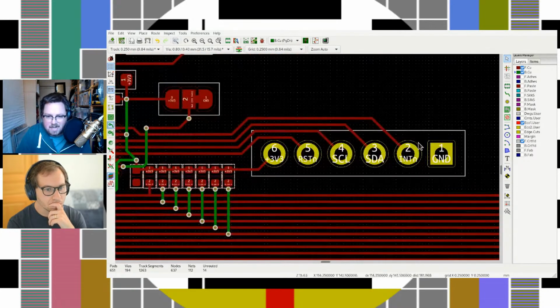And so the only thing that I actually need to connect to my microcontroller board is 2 serial port lines, 1 line to reset the expander if you need to hard reset it, and then an interrupt pin so that the expander can say, hey, I just had a pin go high, in case you want to do some hardware acceleration stuff, but you don't even... Right. The only things you really need are ground, power, and 2 clock lines.